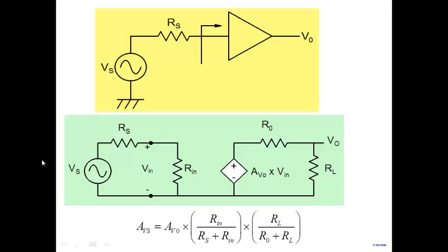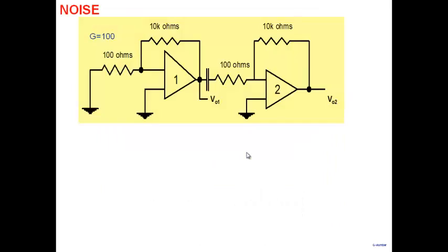In addition to the resistors, there are capacitors also inside the amplifier, and those models would be valid at the higher and lower cutoff frequencies. In the mid-frequency range, you can think of your amplifier as described by these frequency independent elements only, so gain is flat with respect to frequency. So we have learnt two more parameters, the input resistance and the output resistance of the amplifier.